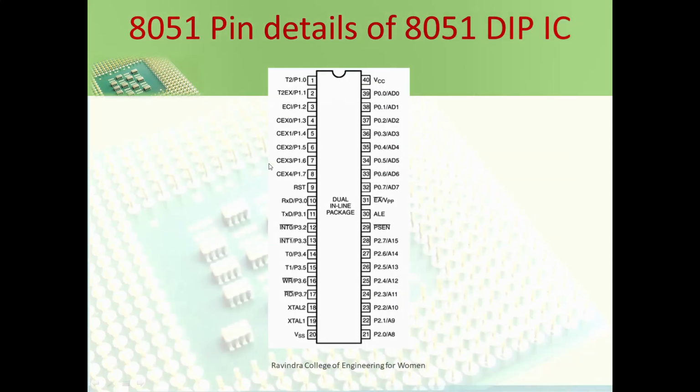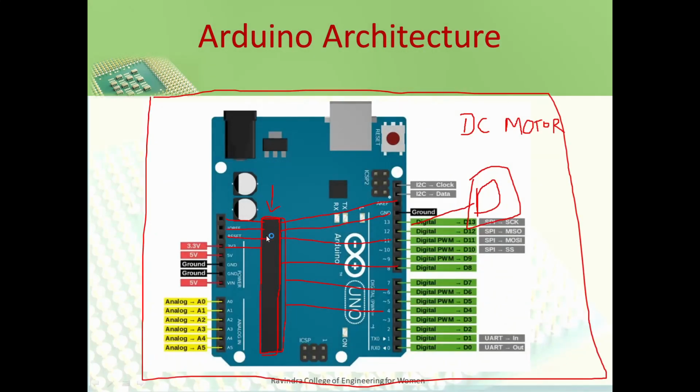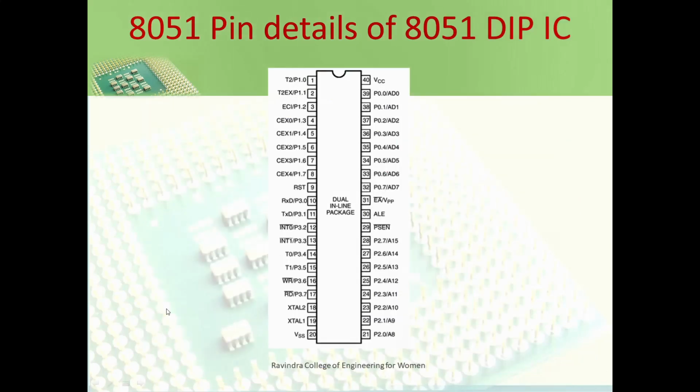Correct. So this is the pin diagram. If I want to expand this, what is the pin configuration of this IC? I can find that this is the pin configuration of the IC. So the 8051 microcontroller is a 40 pin IC. You can find that these pins have been used many times. So port 0 is one port. Then we have port 2, and we have many ports, so that we can connect to this and we can program it. Right. So this is for the 8051 microcontroller.